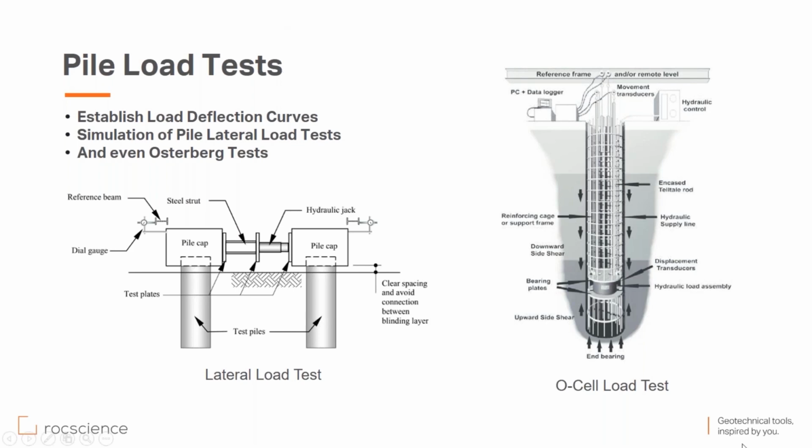And with the new features that we have in RSPile, you can simulate even what is called the O-cell load test by applying the loads at any point along the pile, and you can divide the pile into two parts.